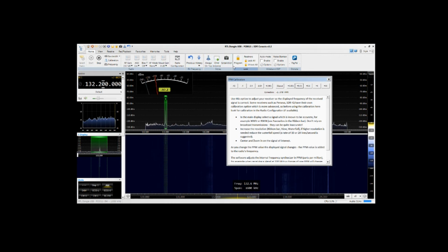I was going to say before, the auto mute is a very handy feature also if you're using an SDR to receive a bandwidth of say 27 megahertz, and you want to talk to somebody. If something comes up, you look at the frequency on here, and then you turn your radio to the channel, and of course as soon as you transmit, you blow this out of the water, unless you stop this all the time.